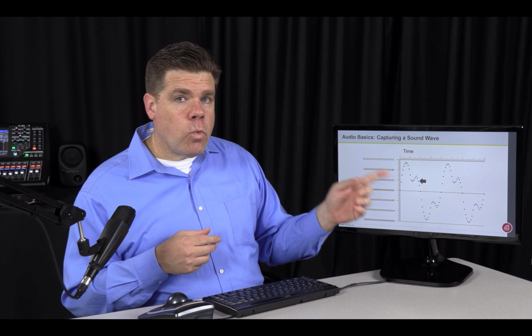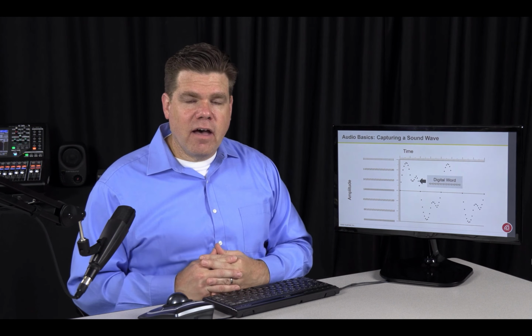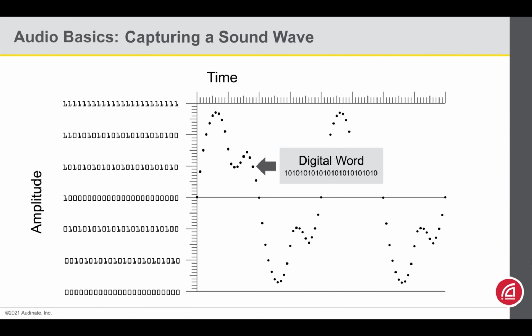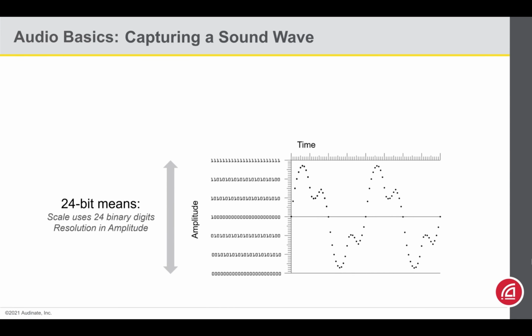But if we're talking about one reading, there might be a very specific term of a digital word. And you might hear people speak of bit depth or word length. That refers to the number of binary bits used to record this reading. Basically, using more bits means we have more resolution. We have more steps on this ladder. CDs operated at 16-bit. Most professional production is done at 24-bit, and some equipment will go up to 32-bit. Dante can manage all of that.